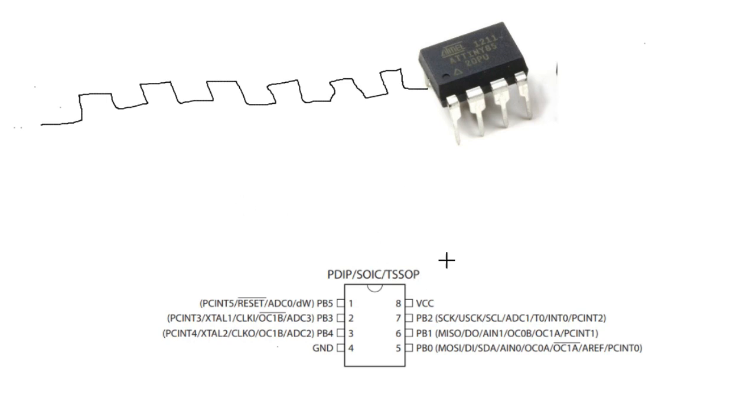In the hardware, there will be a specific pin assigned to take signal from external sources. In my ATtiny85, PB2 is going to be our signal source for the counter. PB2 has the special function called T0. This pin will be responsible for taking the input to increment the counter in our microcontroller.